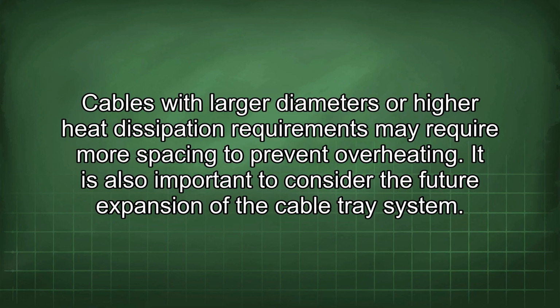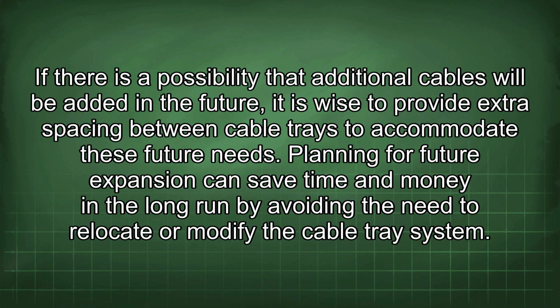It is also important to consider the future expansion of the cable tray system. If there is a possibility that additional cables will be added in the future, it is wise to provide extra spacing between cable trays to accommodate these future needs. Planning for future expansion can save time and money in the long run by avoiding the need to relocate or modify the cable tray system.